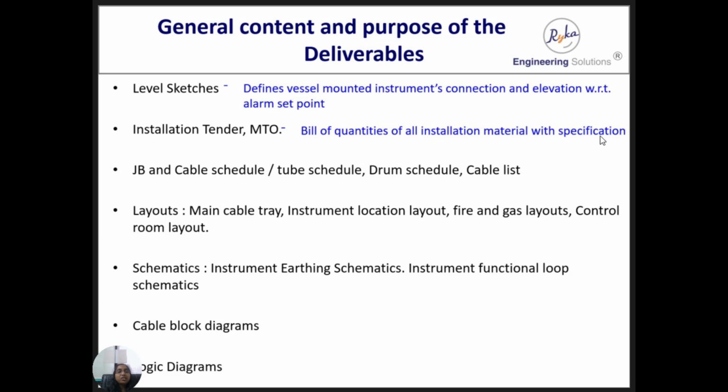Then installation, tender and MTO. So this is basically the bill of quantities of all installation material with specifications, and this is input to the site construction department, so that based on this they can raise an inquiry in the market to appoint a site contractor.